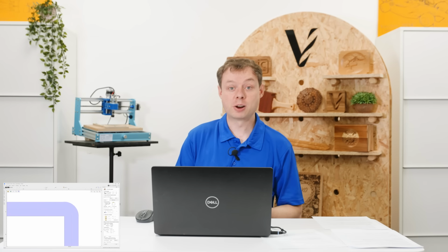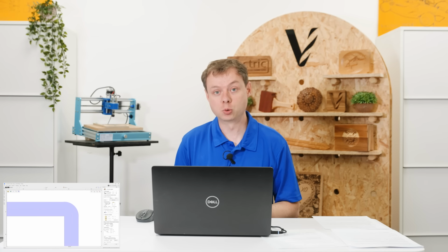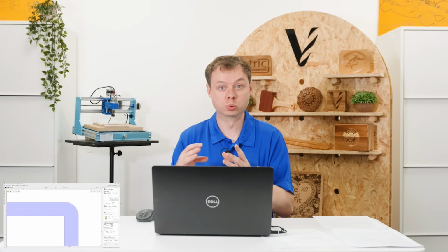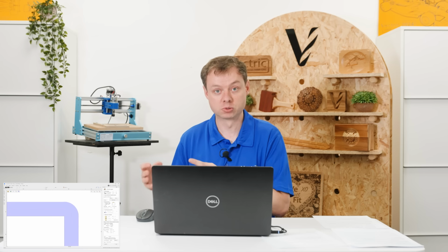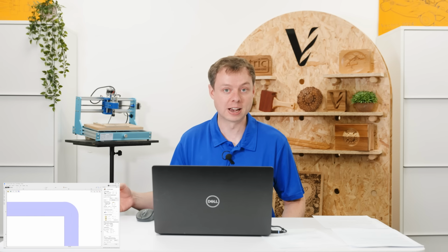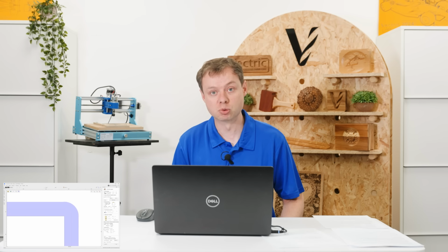That's a good thing to be aware of with the box creator gadget actually, because the imported vectors and toolpaths that are created are auto-arranged. Any changes in the position or the actual tool type, not the settings but the actual tool geometry, will mean that it's recalculated circumventing the gadget. So you just need to make sure that the same allowances have been applied, and using the 2D solid view is a really good way of doing that.